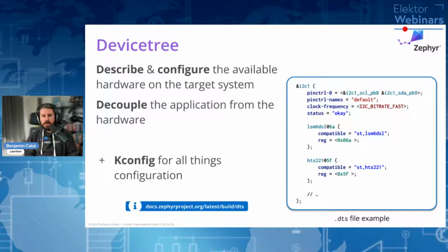what does it map to? What is the GPIO pin that it is mapped to? And more specifically, for this particular GPIO pin, what is the actual GPIO controller that allows you to drive this particular pin, etc. All the things that you really don't want to write by hand. It's usually hidden behind the scenes in something like Arduino, or it's not with some other real-time operating systems, and you have to do the bootstrapping code and the initialization code yourself by calling all the methods from the silicon vendor hardware abstraction layer and whatnot, and that can be painful.